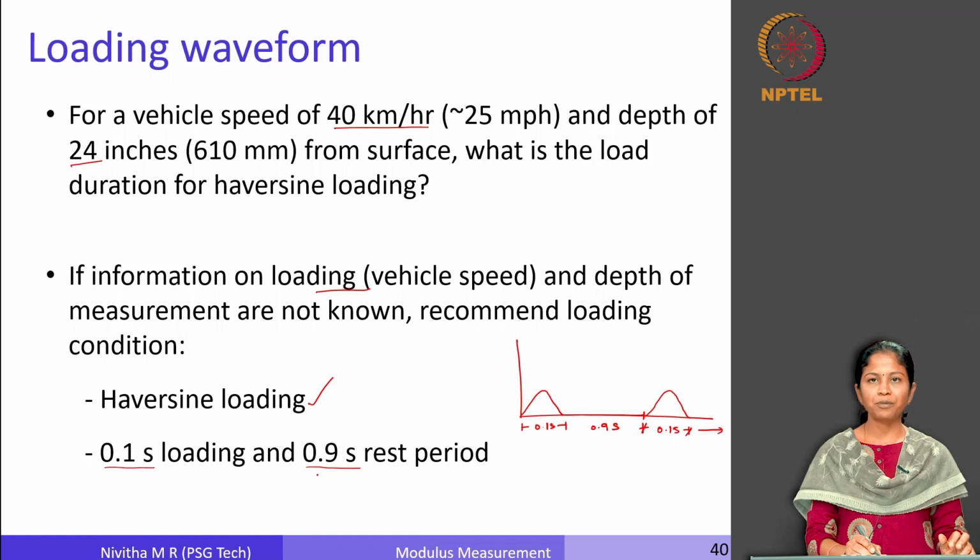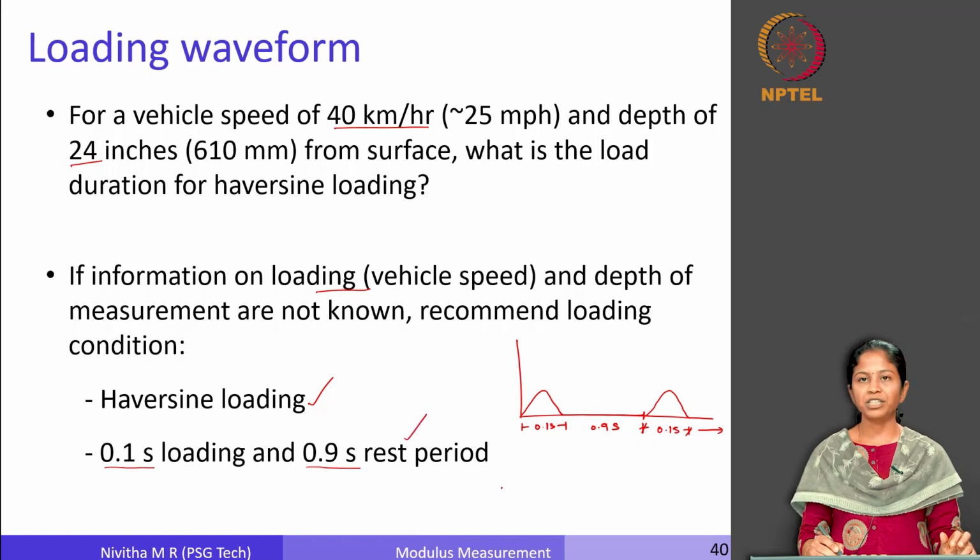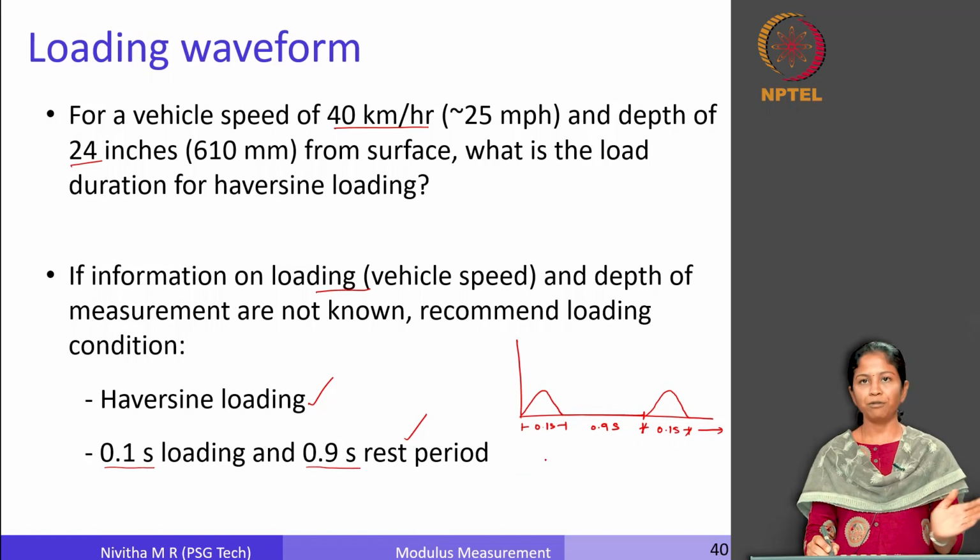And for most test procedures these standard conditions are used, and rarely do people measure all these parameters and use them in the test protocols. So, for now and for the remaining part of this lecture, let us assume that we are going to apply 0.1 second of Haversine loading and give a rest period of 0.9 seconds for these strains to recover.